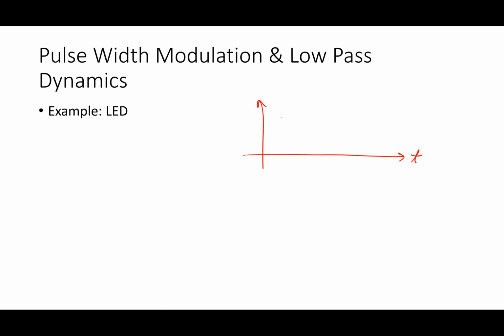5 volts. And then 0 volts. And then 5 volts. And just repeating it. All right. And the period of this thing, T, which is 1/f. Right now, as I have this set up, f is 1 hertz. So basically what you're seeing is this guy is on for half a second and then he's off for half a second, just flashing like this.